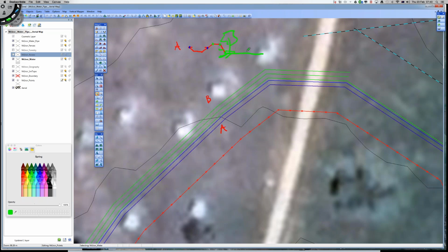Or do I want to have a bit more maintenance, etc.? Let's say I want to have a bit more maintenance, then I'll put the tree out here as opposed to right at the toe of the embankment. I'll do that so there's a distance that I can, say, fit a tractor or something down here to mow the grass, if that's what's going on, right? There's that sort of thing that might happen here. That's a farmer on a tractor.